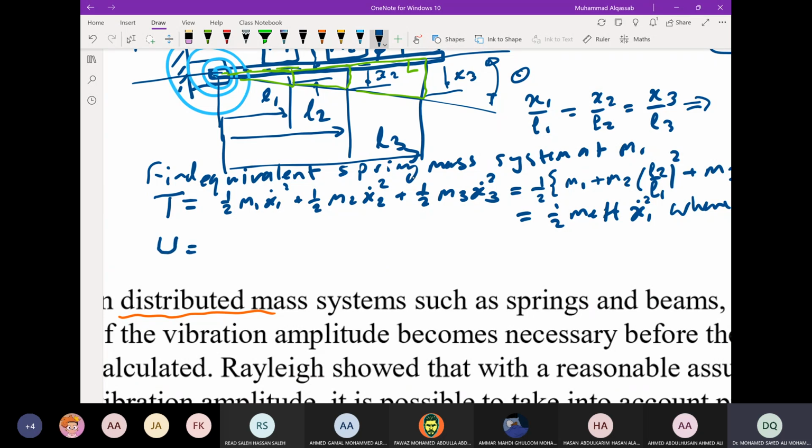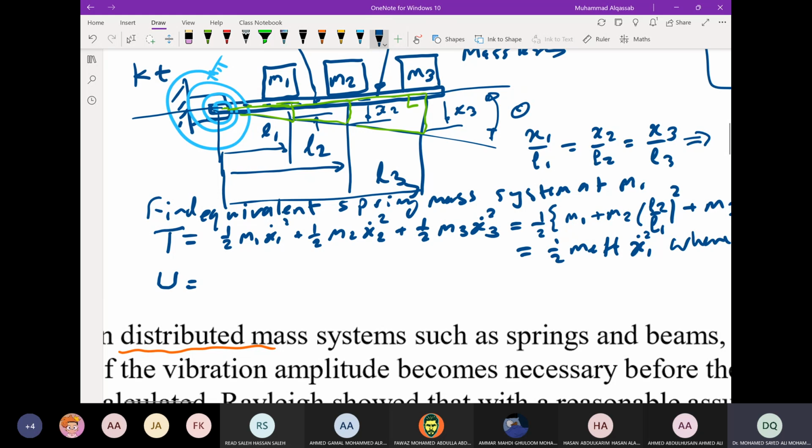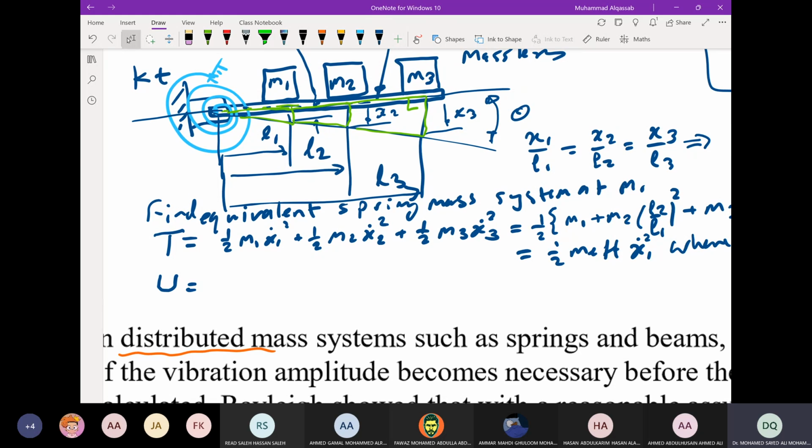Potential energy is what? Of course, do not put mg, because the M1g and M2g are balanced by the torsional spring in equilibrium. Whenever you have a rigid bar supported horizontally that carries masses, the equilibrium line is either horizontal or inclined, but it means that the weights are balanced by the forces in the spring or the moments in the spring.